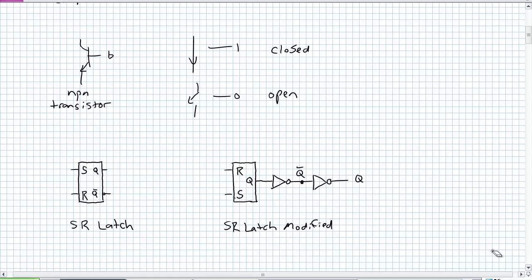How does an SR latch work when it's upside down? Well, exact same way as when it's upright. When I'm neither setting nor resetting it, what does Q do? And what I'm talking about is this Q right there. Because look at this string of inverters. I know it's kind of a pain, but I'm trying to stick with a traditional diagram for the 555. What happens to that Q? Well, it's inverted, so that's not Q, and then re-inverted again, so that's Q. I know it's kind of a pain, but we have to use that not Q signal.